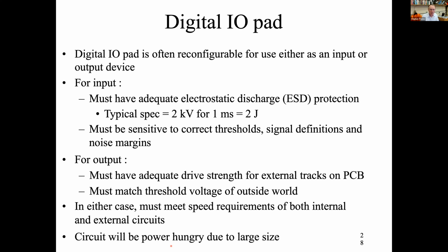It's got to be sensitive to the right threshold, so that's the external circuit thresholds, and external circuit signals have got to work going in. Output, we've got the same sort of problem. It's got to have an adequate drive strength, and it's got to match the threshold voltages for the outside world. In both cases, it's got to meet correct speed requirements, and it's going to be a big circuit compared to these little tiny transistors we've been looking at for the VLSI circuit, so it's going to be power hungry as well.